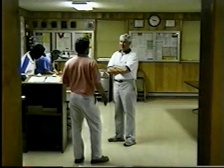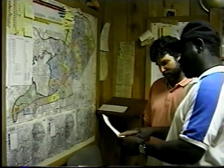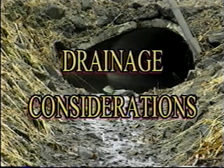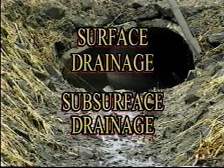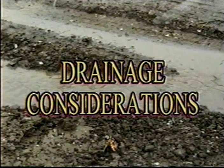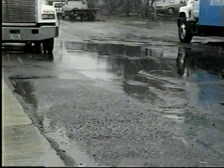For these reasons, the quality of your maintenance and rehabilitation program is key in helping to keep water away from your roads. This film will discuss drainage considerations including surface and subsurface drainage, drainage systems, and inspection of these systems. Pavement deterioration that starts with poor drainage cannot be effectively corrected by either construction techniques or maintenance procedures. The drainage problem must be solved first.